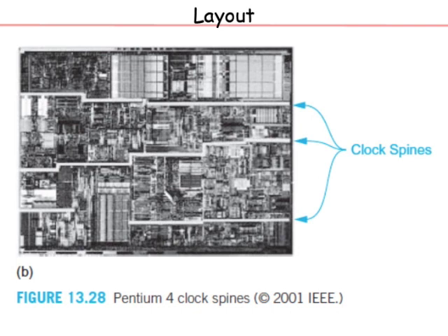So it also brings out another important thing, that you can now define global and local skew and jitter. If I have a local launching flop and a local capture flop, skew might be small, whereas globally it could be larger. So you can do much finer timing analysis by taking into account all these kinds of aspects.